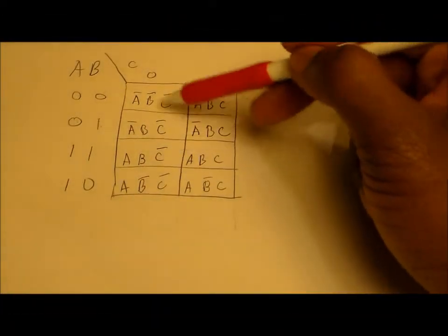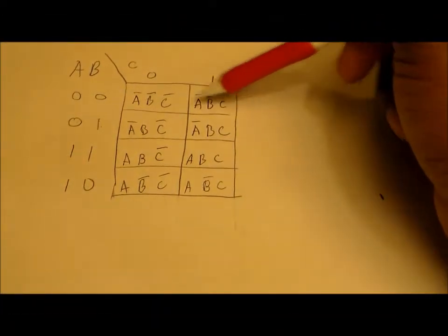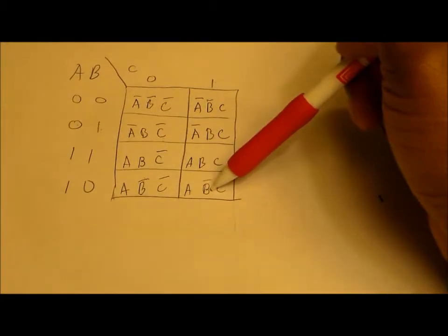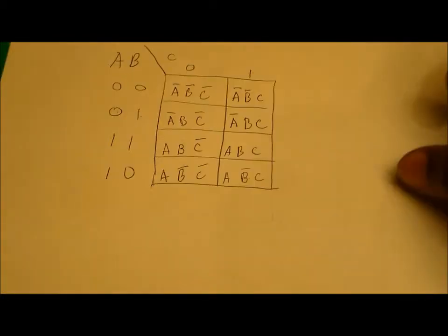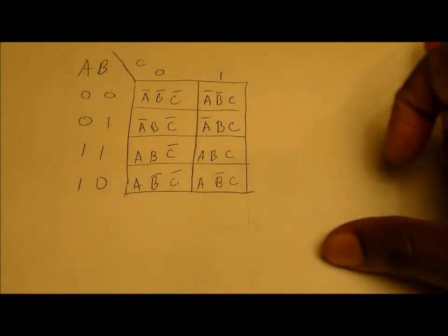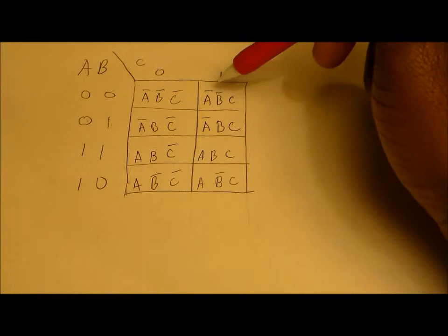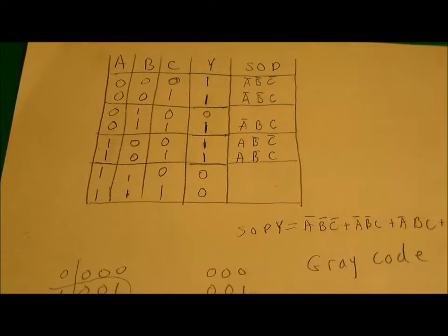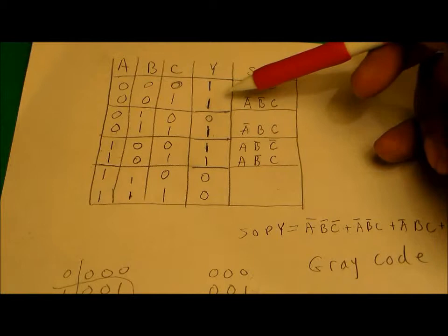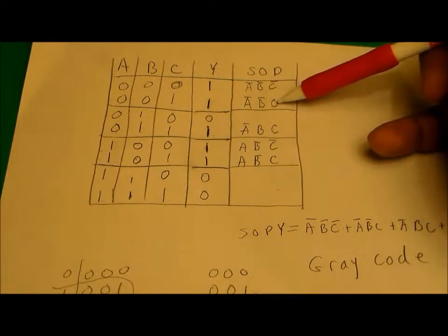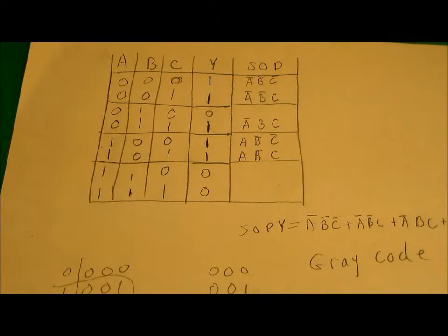So that's what we'd have in each of these positions. Now in these areas of the box on our truth table, we're going to put the ones, since we're trying to do a sum of products representation of our circuitry based off of what we had a little bit earlier. We're going to put ones in these positions where they correspond to the ones from this original truth table. Again, we had a 1 in this position where we have A naught, B naught, C naught, a 1 here where we have A naught, B naught, C, and so on and so forth. All right.